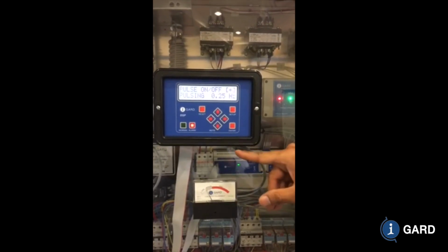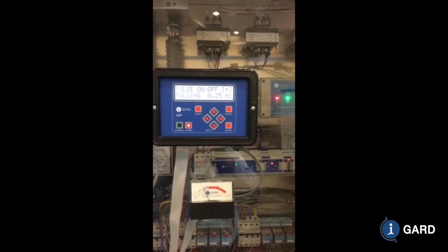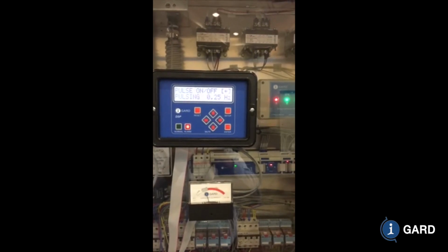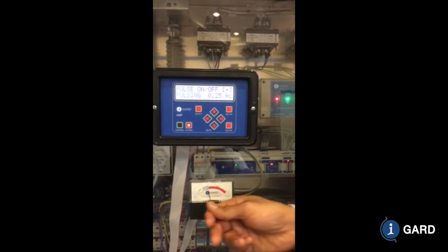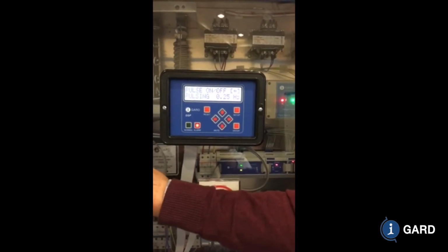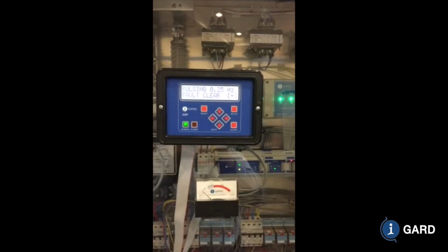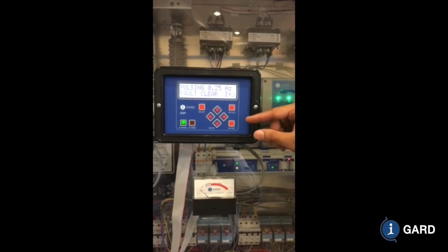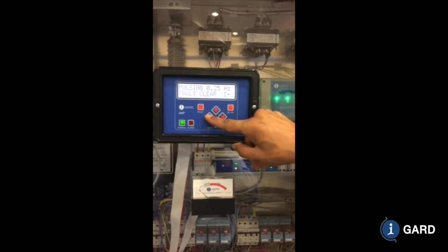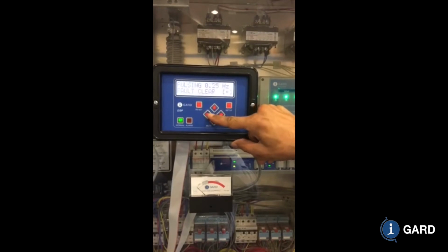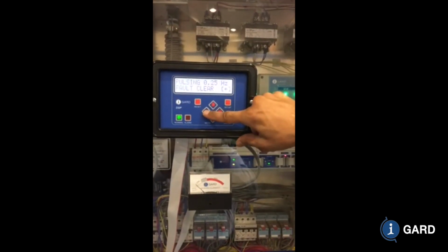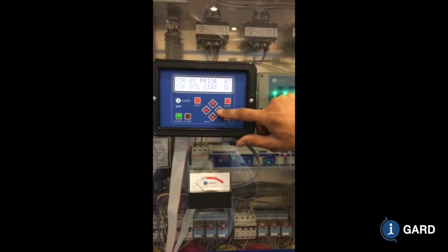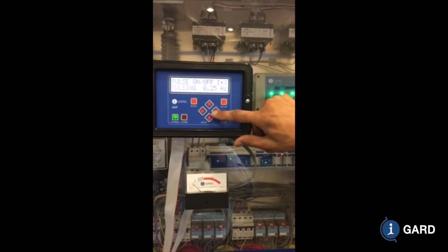So you turn pulsing on. You do that process of putting a current sensor, looking for that pattern, and you find the location of the fault, and you clear that fault. You find a way to take that equipment down and rectify the situation. So you can turn pulsing off. So that's how pulsing works.